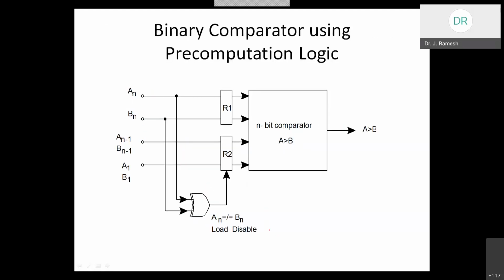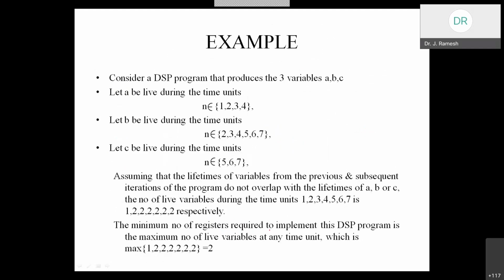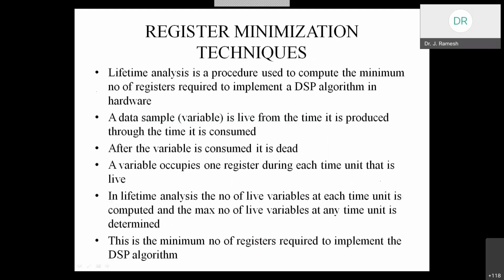In pre-computation logic itself, we have several architectures, and we can choose some of them based on our application. And we can minimize the registers also. Register minimization can be done by lifetime analysis. Lifetime analysis is a procedure used to compute the minimum number of registers required to implement a DSP algorithm in hardware.